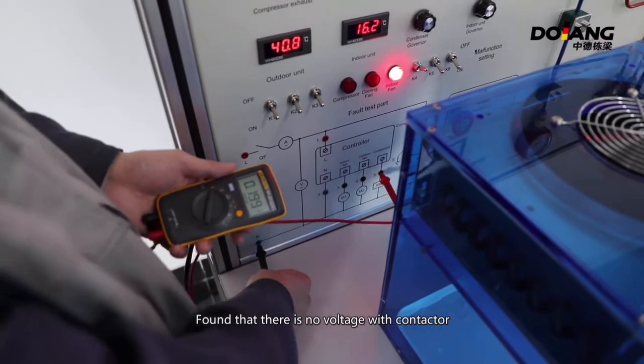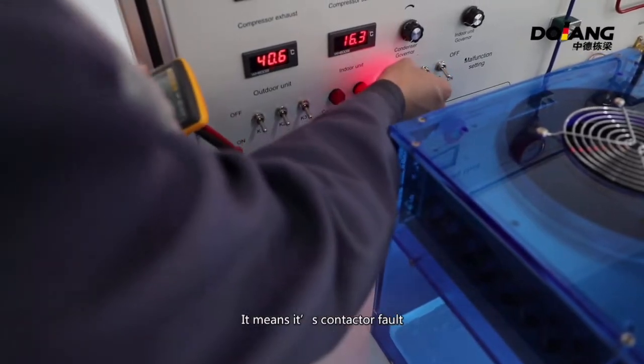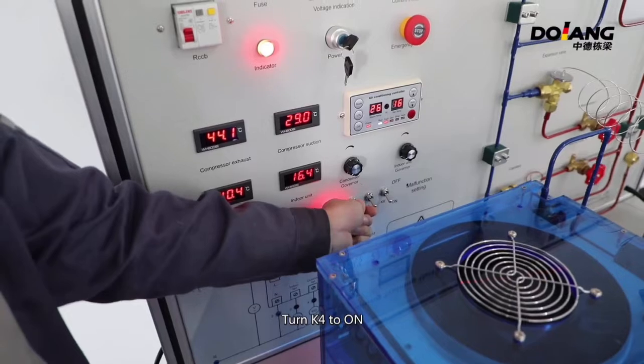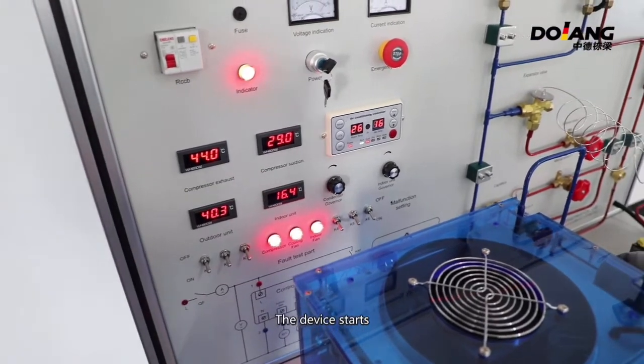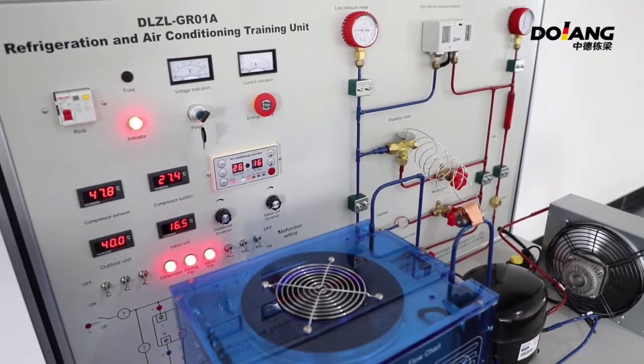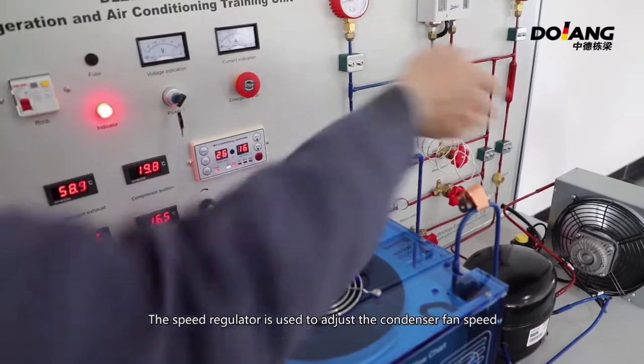Found that there is no voltage at the contactor. It means it's a contactor fault. Turn K4 to on. The device starts. The speed regulator is used to adjust the condenser fan speed.